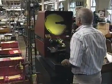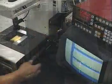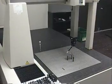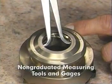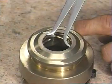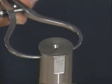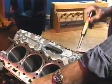Additional measurement tools include optical measurement projectors, vision systems, coordinate measuring machines, and others. Non-graduated measuring tools and gauges do not have linear or angular graduations marked on the tool. These tools are generally used to transfer measurements to or from a graduated measuring tool, or as a pass-fail check comparison to a standard.